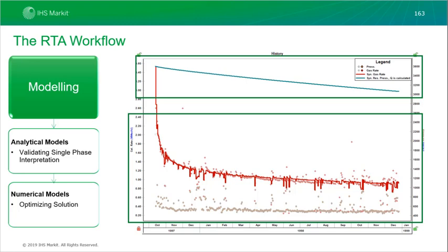These are our measured gas rates and pressures, and the red line here represents our simulated gas rates. Now, with the reservoir signal parameters that we've extracted through our interpretation, what the software does is try to recreate a simulated rate that overlays onto your measured rate, indicating that we have a good history match to our production data. It's also important to note that you can actually create a history match not only to your rates, but to your flowing pressures as well.